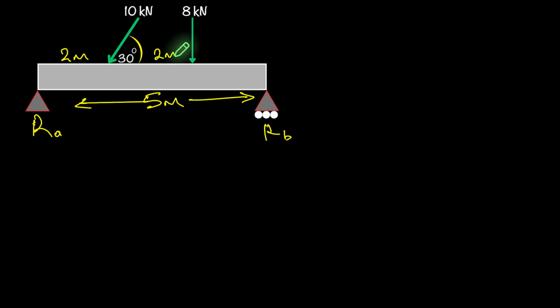Now, one very important thing that we need to do is to look at the reactions for the supports, because a lot of times I see this part get neglected. So let's just look at it real quick. To the left, we have what's called a pin support or pinned support. What it does is prevent movement in the horizontal and vertical direction.